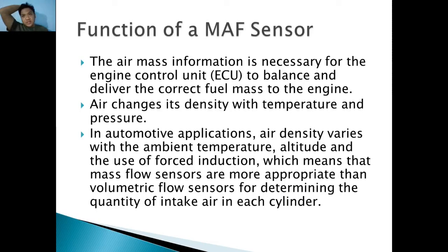Okay, a little information. If you remember, this is the main problem with carburetors, where if you are at a high altitude, it feels like the engine is not getting enough air, and when you're at sea level, it feels like the engine is running a little too lean. So this is the solution of electronic fuel injection: to measure the air flowing inside the engine to set the air-fuel mixture ratio.